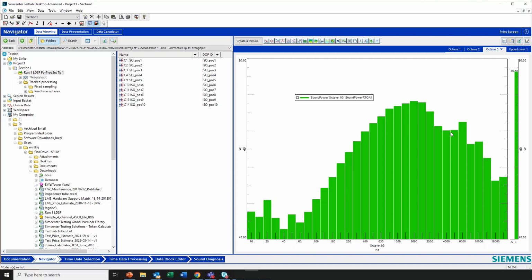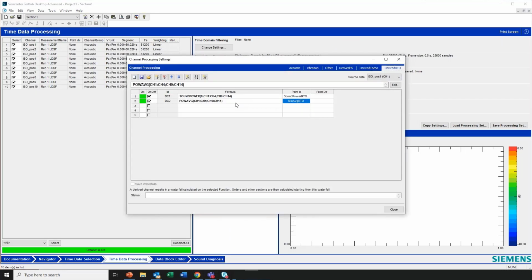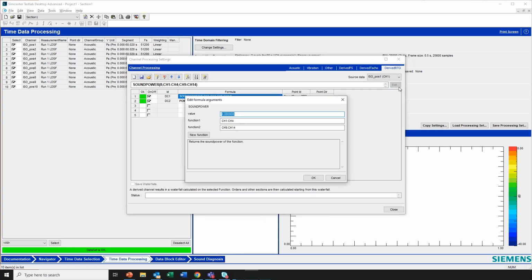Yes, Scott, I was going to just say that if you don't want to apply any of the correction factors, the K1 and K2, that will be for some measurement like in an anechoic chamber. There is very little influence from background noise and the room is not reverberant. So all the sound radiating from the source is absorbed by the walls, right? And it's not reflected back. In such an environment, you don't need to apply the correction factors because the background noise is well below the measured sound pressure level and there is no reverberation. So K1 and K2 can be ignored in that case.